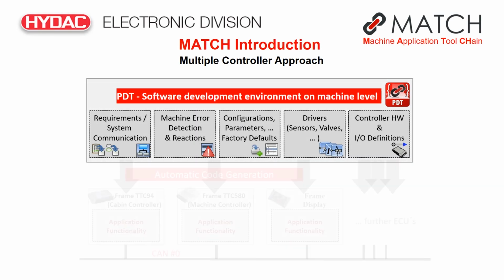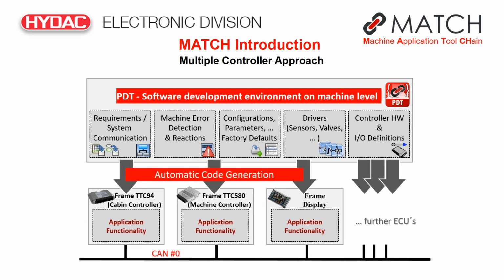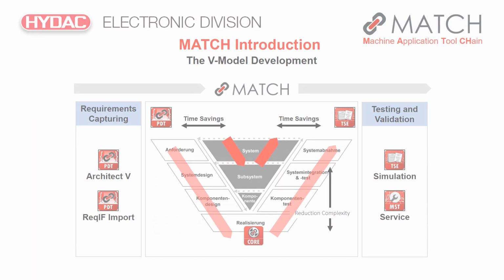MATCH has the ability to integrate multiple controllers. If the project requires more than one controller and/or an eVision display, MATCH will generate each of these separate modules and manage the CAN communication and functionality between the respective devices.